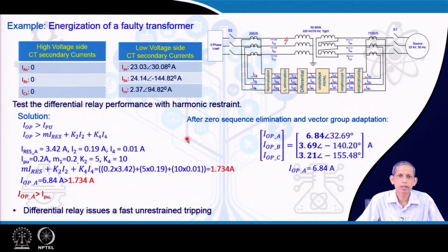Now, take another example. Let us say an internal fault is present in the transformer, it is not loaded, and we energize it. If this is the situation, the relay should clearly know that this is an internal fault. So, the relay must trip, even though it may find some inrush behavior. That must be ensured with whatever restraint we are observing.